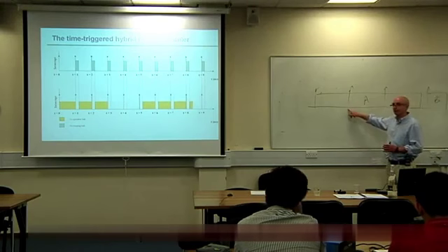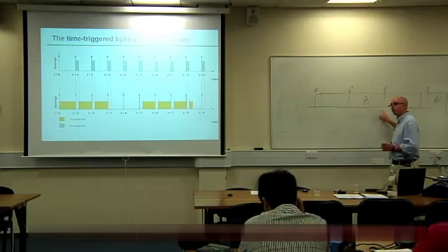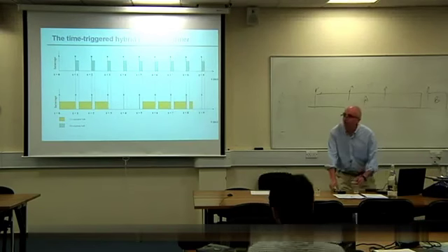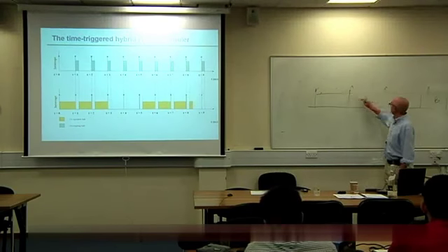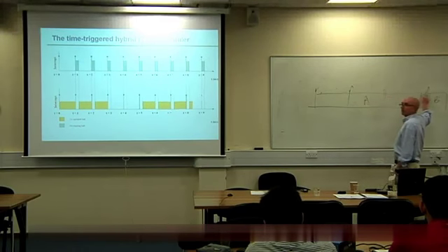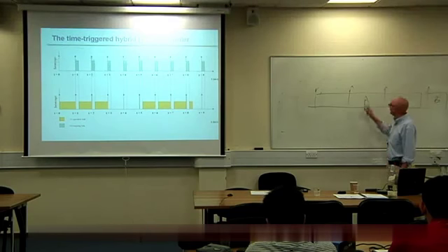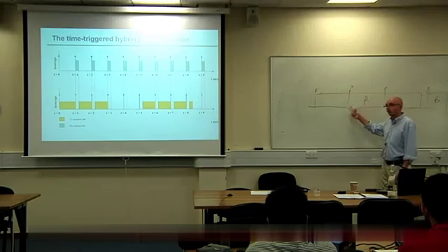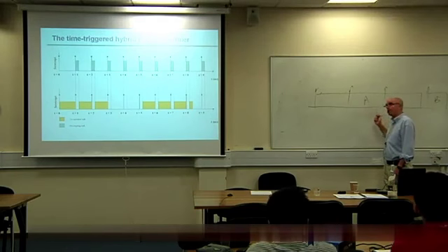It might give us a small disruption to the timing behavior of A that we would need to be aware of. And we might decide in an ideal world that we want to run this on a piece of hardware that doesn't force us to have these ticks. So we could omit these and just go straight to the next one, changing the interval between the ticks, but we wouldn't have to. We could run with this simple model, and if we were willing to tolerate the level of jitter in these task timings that would result from these brief interruptions, we'd be fine.